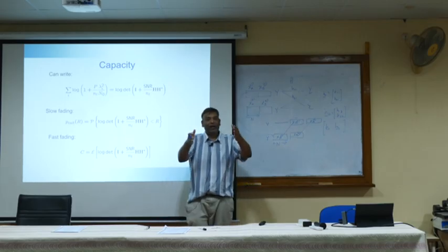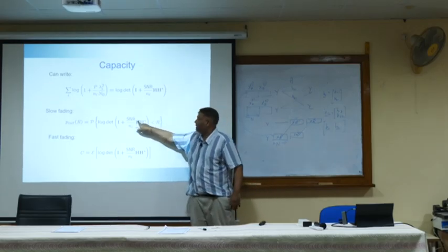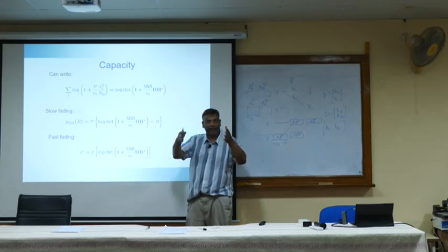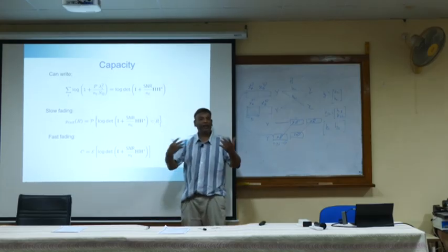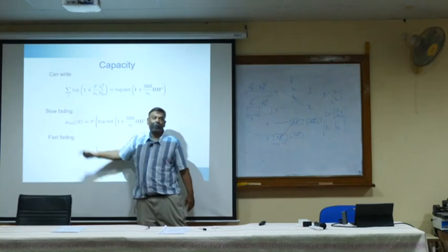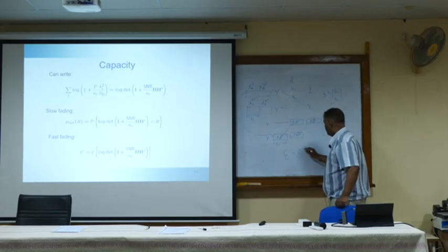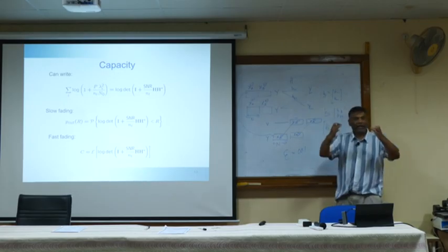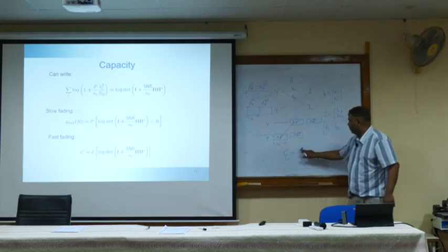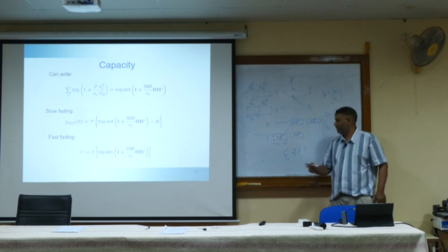You are in outage because you designed a communication system saying it is going to support R bits per second, but H is random and became a deep fade, so the capacity of that channel in the deep fade does not support R. The probability of that event is the outage probability. Let's say the outage probability is 0.01: if you take 100 realizations of the channel, one of them is in outage, so 0.01.